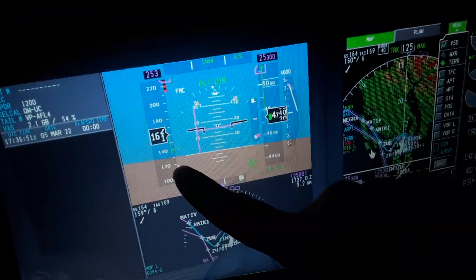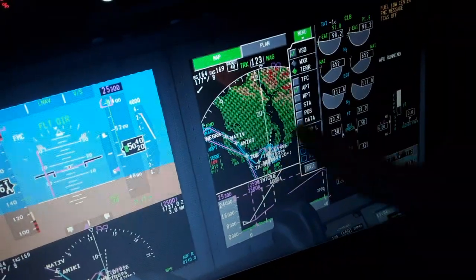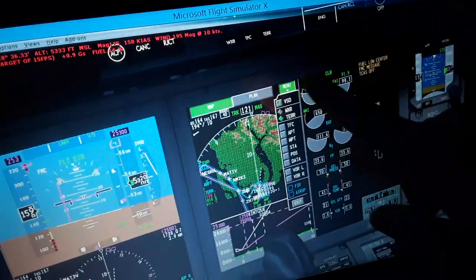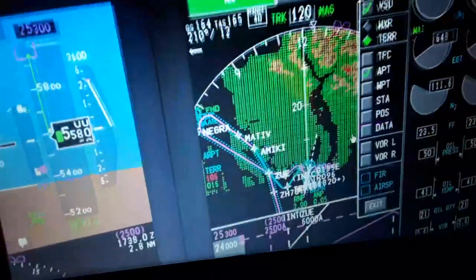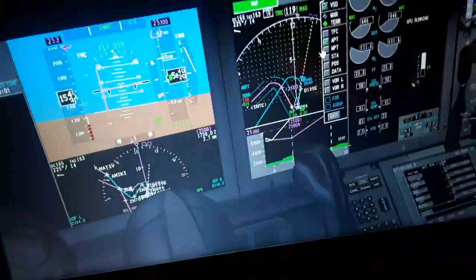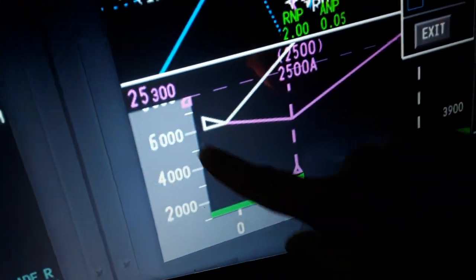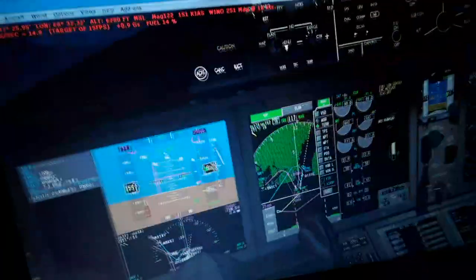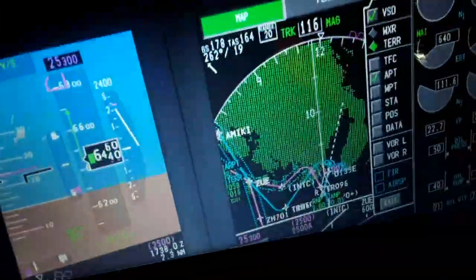We lower. We have the stall speed here, the wind direction and speed, the vector. We can see the terrain around you, the flight plan. We have to fly all the waypoints, the engines indication. So you can see how far above the ground we'll be flying right now. Over here we change the range. You can see the ground is below us with the terrain. We are like 4,000 feet above the ground. That is displayed with green here. As you can see, maybe better indication.